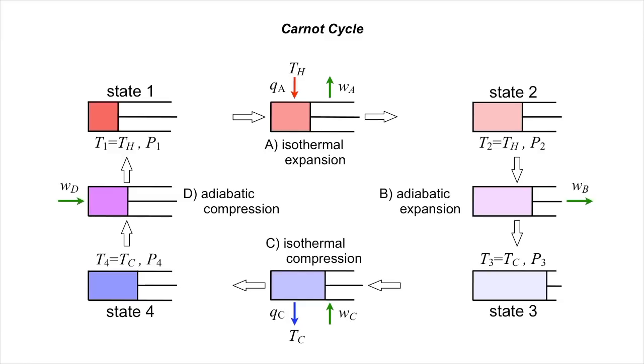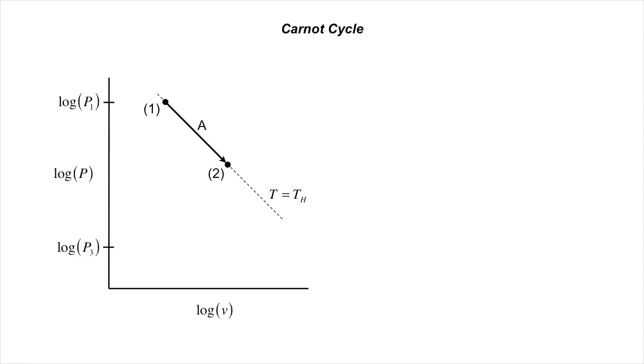In this strategy, pressures P2 and P4 are chosen to ensure that the adiabatic expansion and compression steps hit their desired temperature and pressure targets, P1 and P3, at Th and Tc, respectively. The first to sketch these transformations on a PV diagram was Émile Clapeyron, who in 1834 analyzed this process quantitatively based on the properties of an ideal gas.